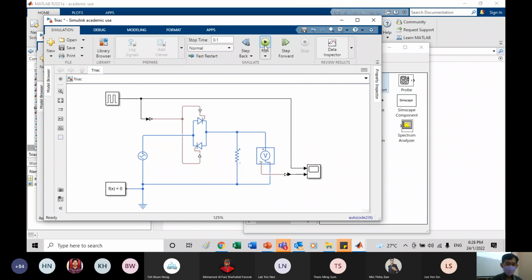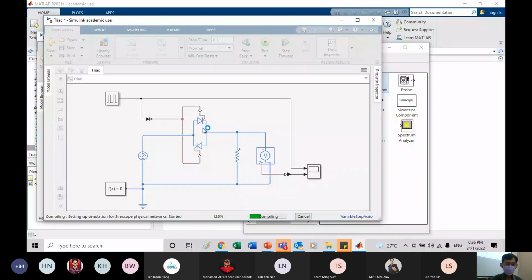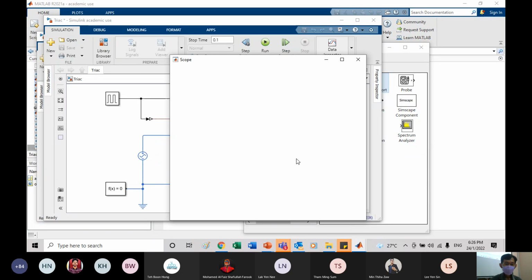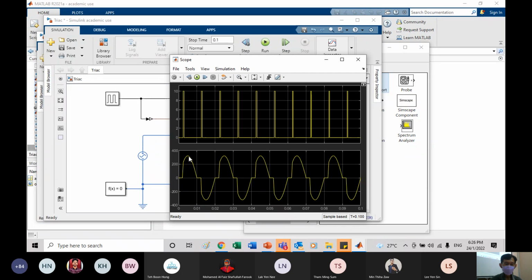So with this one, now it will show you that with the Thyristor you can control the power. If you have a full sine wave going to the load, you get full power. Now I chop this off, I get less power to the load. This is how you control AC power to a resistive load.